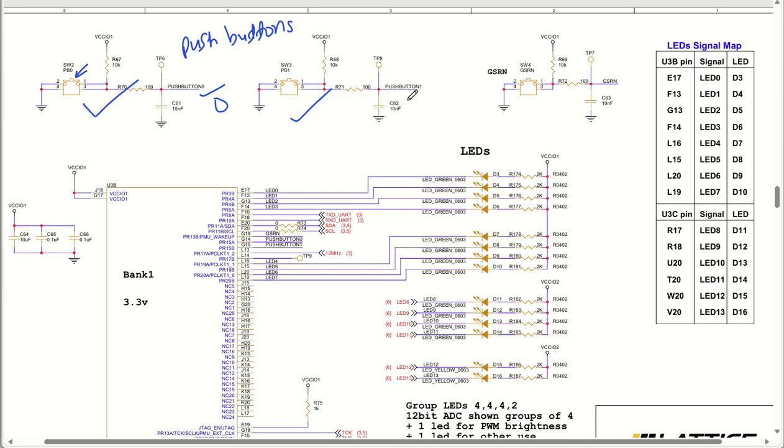Similar functionality will be for push button 1, and we have a general purpose push button 1 more, which can be used for general purpose as well as some wake up application. Okay. Then we have transmitter receiver UART, and we have SDA and SCL lines for I2C application. We have a 12 megahertz clock generated at the FPGA chip that can be used as a clock input.